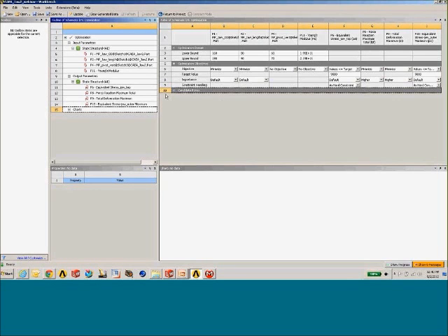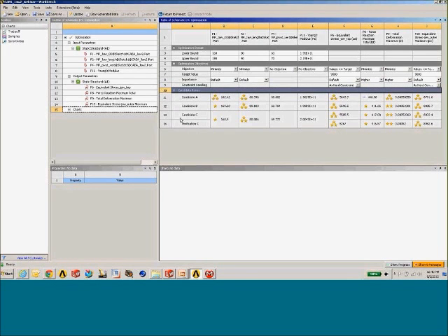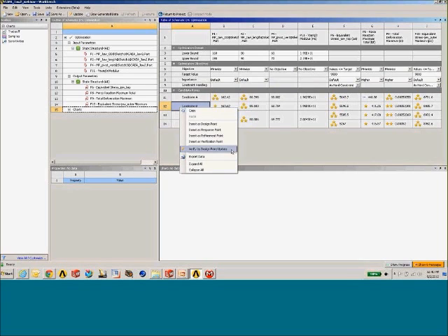So I set up my goals. I then generate candidate design points, or curve fits, and I can look at the response of those candidate design points. And again, these are values of the output that are evaluated from the curve fit. If I find a particular design point that I'm interested in, I can then verify it, or effectively send these input parameters back to the mechanical environment and get a deterministic response that I can compare to my curve fit. So the row on the bottom here, the verification row, is an actual finite element solution output, and I can compare that to the curve fit value to evaluate the goodness of fit in my response.